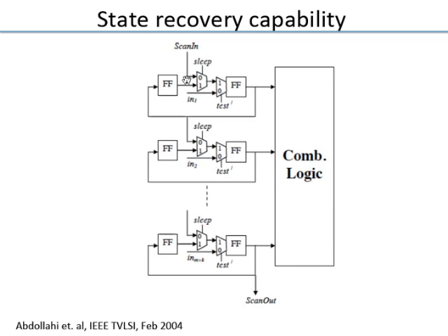So if you see out here, the standby state vector is also scanned in. It's not hard coded, it's scanned in. Then it is stored out here. And then it's like a ping pong. You put it in here when you enter standby state. When you come out of standby state, you put it back here.